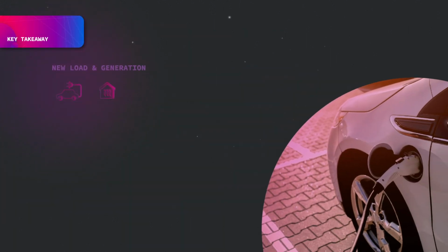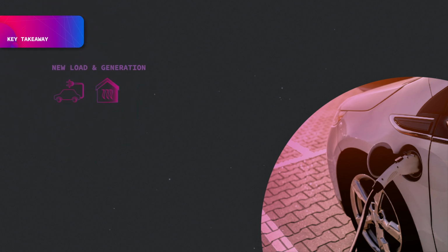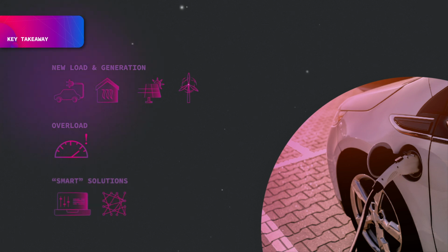To conclude, new loads, such as heat pumps and electric vehicles, can lead to new and partly unpredictable consumption patterns that can cause overloading of some elements in the network. On the other hand, distributed generation can cause overvoltages in networks with insufficient observability and controllability. In terms of investments, planning and dimensioning network to satisfy the highest requirements is, in some cases, not economically feasible. Therefore, smart solutions can be implemented to solve a problem of overloading.